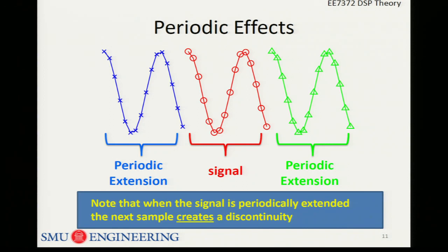Well, let's take another example. Now, if you were drawing a cosine signal, would you expect to jump from this blue one directly to here? That doesn't look quite like a natural progression. I would think it would look more like this side here, where it would jump up and then take a few samples to come up to the top. But when we do this with the DFT, we're imposing this discontinuity.